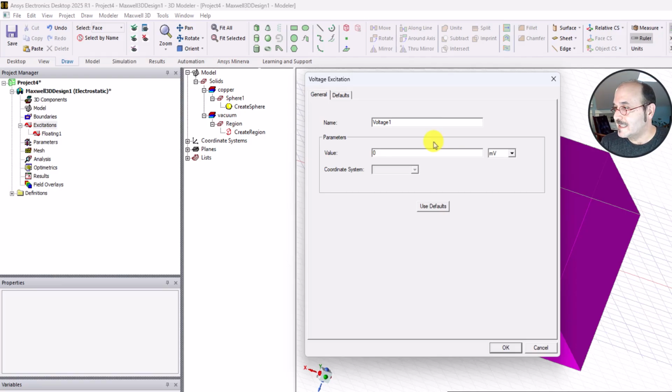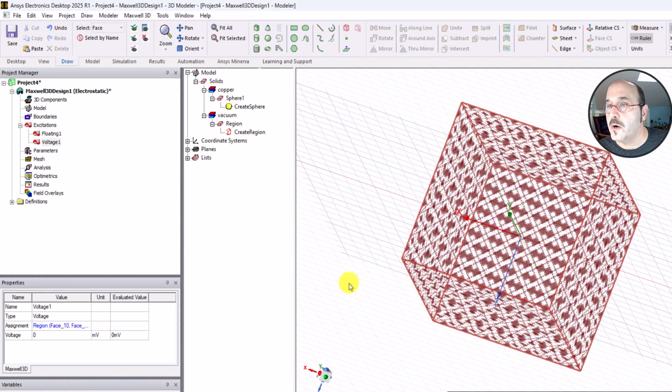And it's basically the same as approximating, as if we go out to infinity in the real universe. I'm saying make infinity close by, and that should give us enough of an area to evaluate fields within that same 100 millimeter radius that we did earlier in the analytical part without corrupting the results. And I'll explain that as we get there later on. So for now, I'll just say OK.